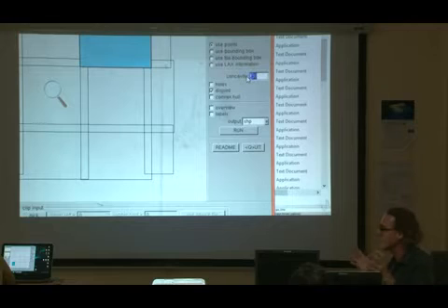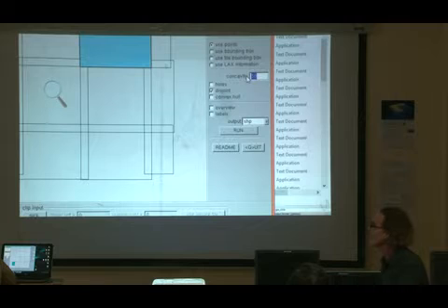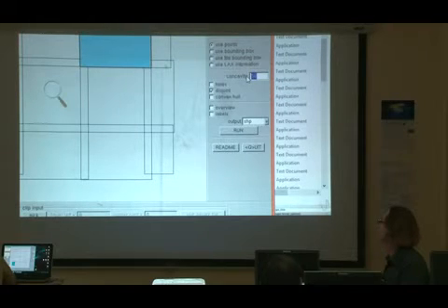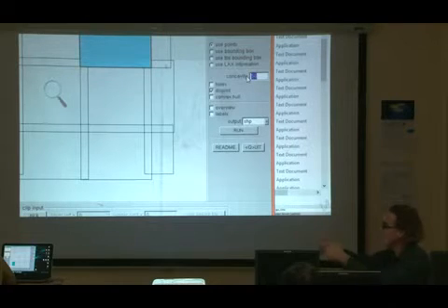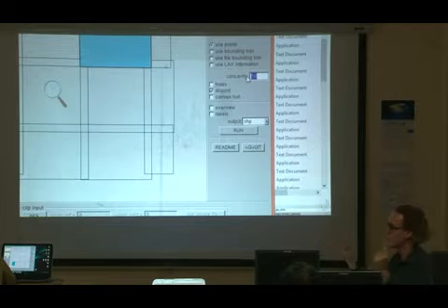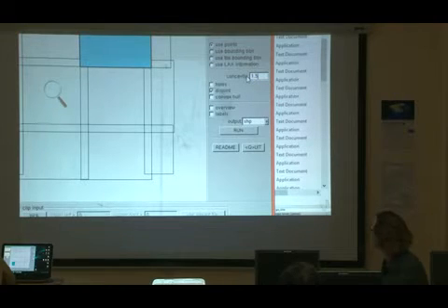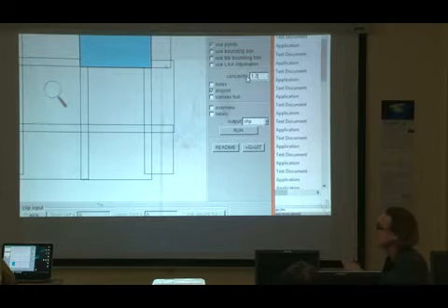And the concavity is sort of the granularity in meters of how close I think my buildings are standing next to each other. I can't make that much lower than the spacing of the LiDAR pulses. It needs to be like double the spacing of the LiDAR pulses maybe. And it shouldn't be too much bigger than the distances between the buildings. Otherwise the buildings will become one building because they're too close to each other. So I don't know what's a good number right now, maybe 1.2 meters. This is something you experiment a few times with practice. We don't experiment today because we don't have that much time.